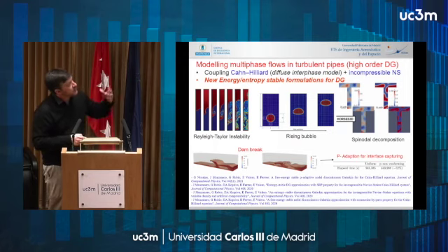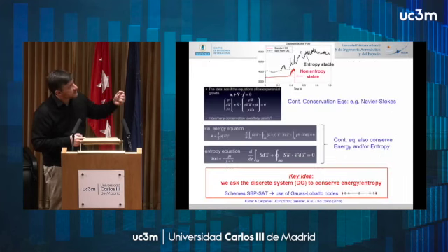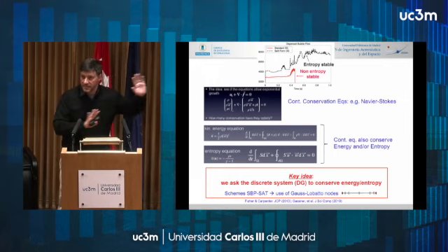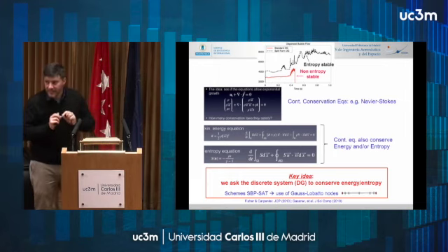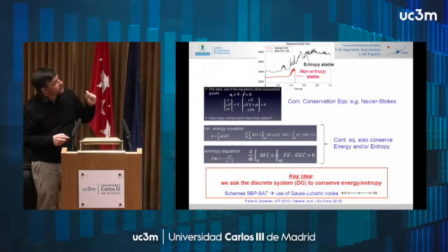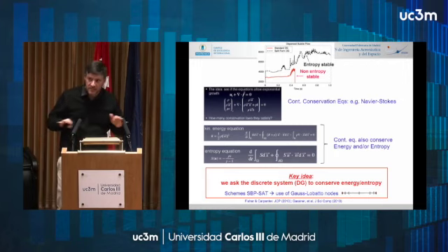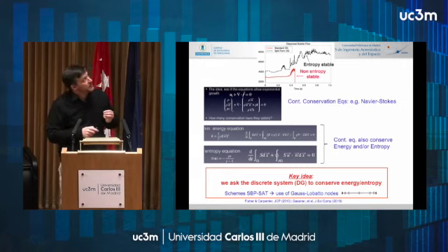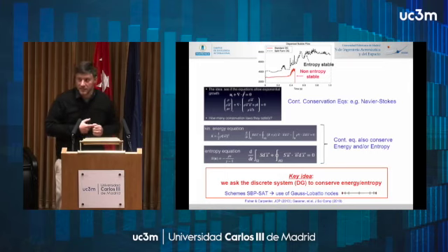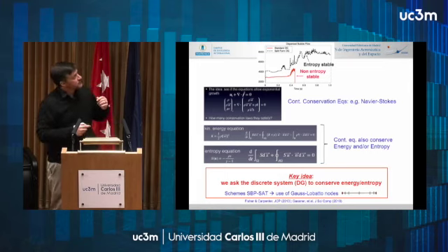And there's a particular feature that I haven't mentioned. Let me just explain very quickly. Those are almost the only equations that I have here, and you don't even have to understand them. So the key idea to do under-resolved flows is that typically, if you run these multi-phase simulations, if everything is well resolved, you have a lot of accuracy at the interface, everything will run smoothly, and you get a converged solution. If you don't, if you have aliasing errors because you don't have enough accuracy, what's going to happen is that it's going to blow up, right? And you're never going to get a stable solution.